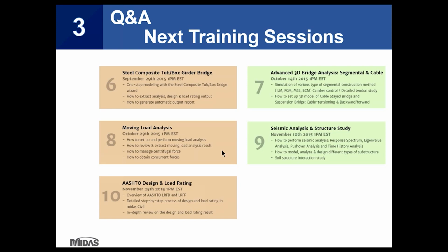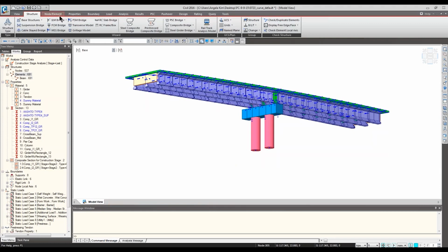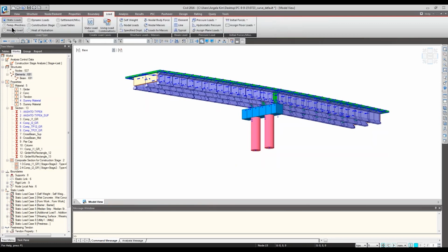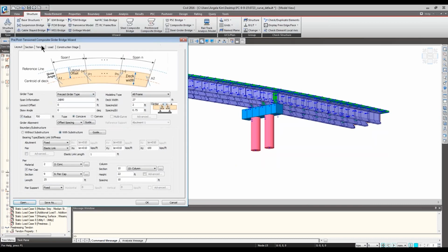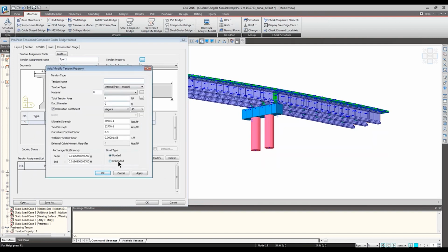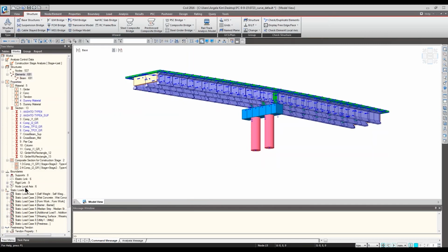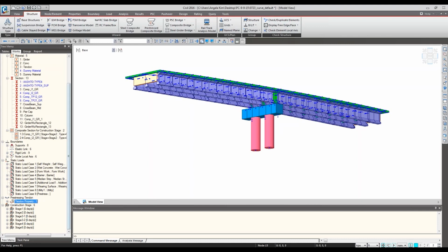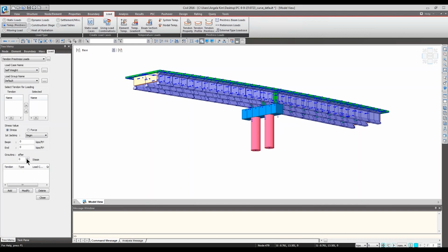Oh, so debonding, this portion, I guess I went really fast. When I define my tendon property, remember within the wizard, over here, I could define the tendon property, right? For bonding and debonding, you can control the bond type here. When you go to tendon pre-stress, you can define when you want to grout it, and also whether it is bonded or unbonded.